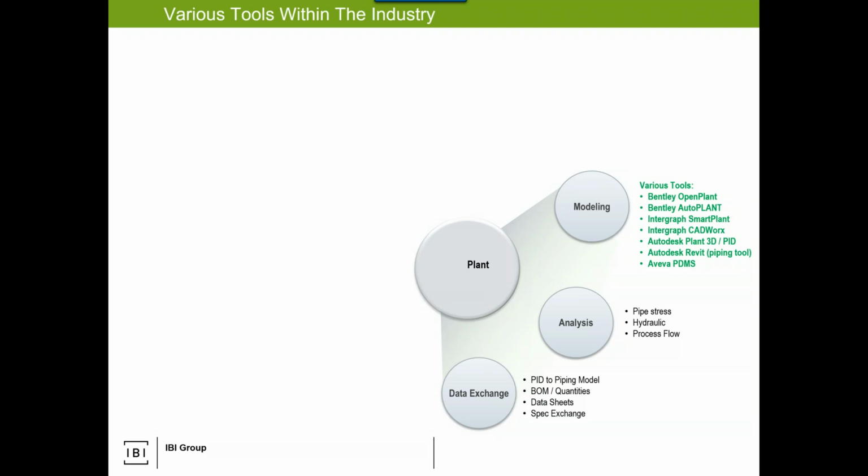Pipeline number one, it's going to have 5 valves, maybe a tank, maybe a pressure indicator, maybe empty into a filter, and maybe a chemical injector. All good. I'll show that simple line, little markings for all that stuff. Well, the P&ID to piping model is going to tell me, hey, looking at your P&ID, you said it's going to have 5 valves. Looking at your model, you have only 4. You're missing a valve or your P&ID is wrong. I can address it. Immediate quality checking between my P&ID and the model.